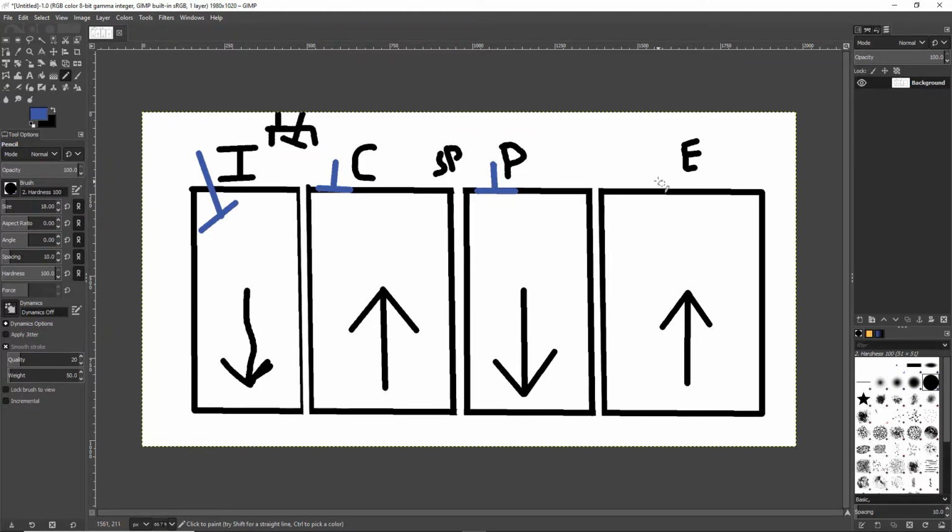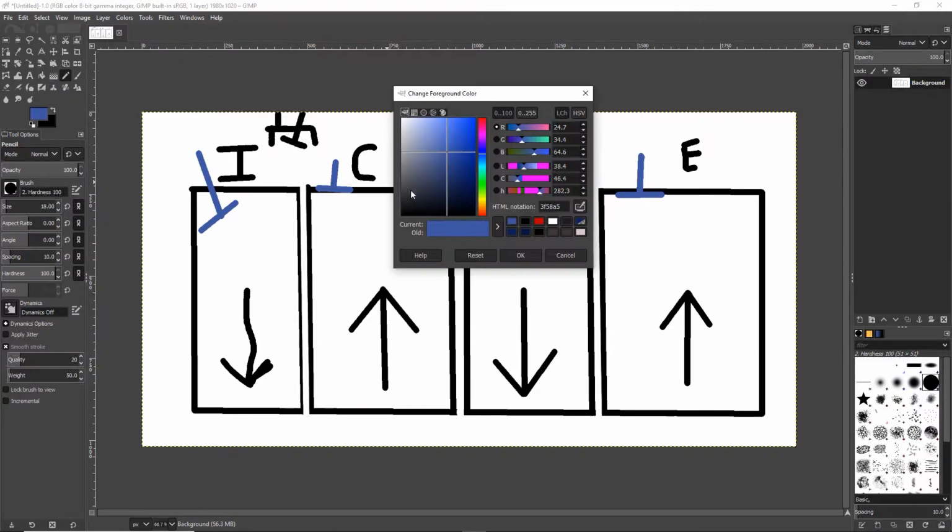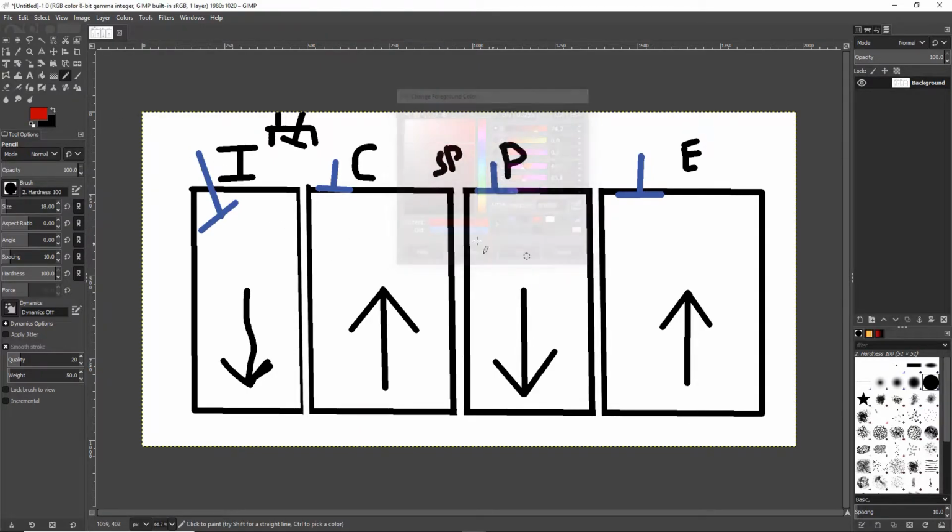And then over here, exhaust stroke, we burned it in the power stroke, now it's spent air and fuel. I don't want that to go back in the intake, I want it to go out the exhaust. So that's our intake stroke, and we'll do red for exhaust. Over here, I do not want you open on the intake stroke. I don't want to pull exhaust in, I want to pull fresh air and fuel in.